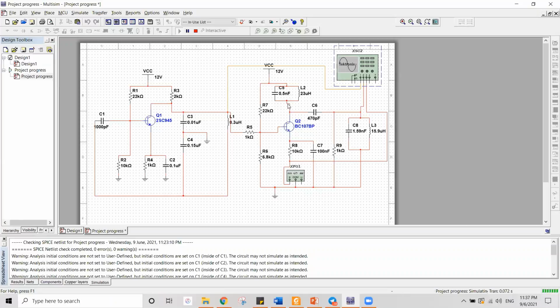It is the process of changing the amplitude of a relatively high frequency carrier signal in proportion with the instantaneous value of the information signal. The information signal we tap from the Colpitts oscillator.